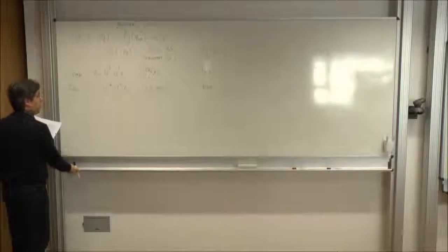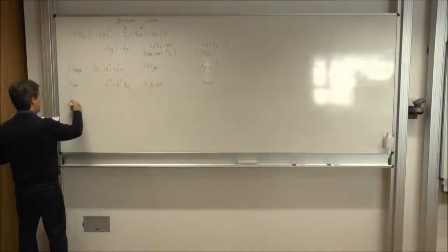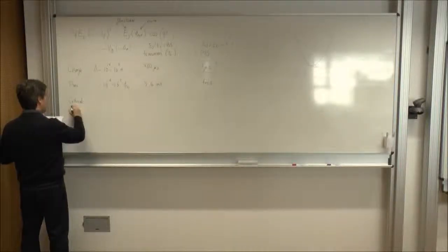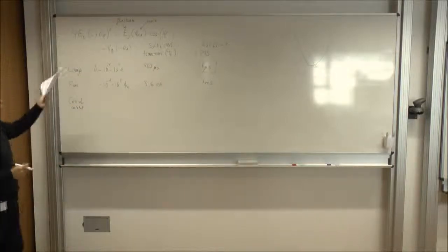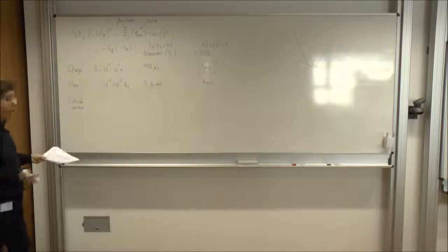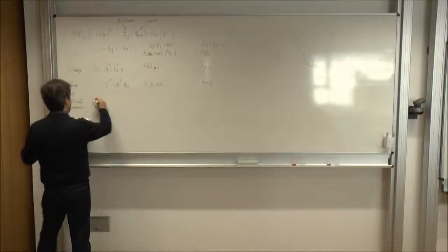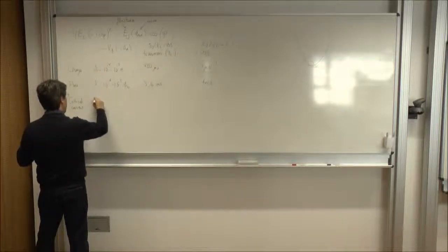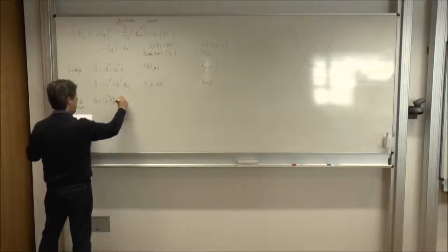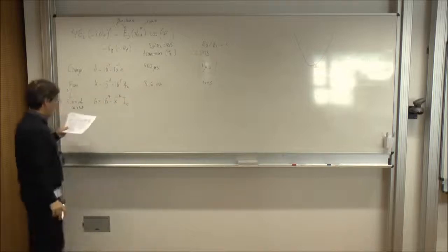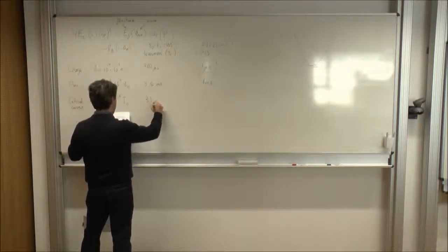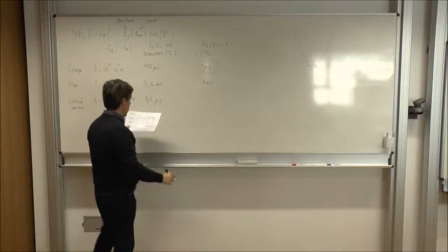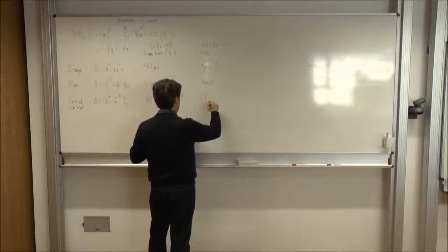But there is another source of noise, which would be critical current fluctuations. Your Josephson energy fluctuates somehow. These are now the parameters that appear in the slow noise, 10 to the minus 7 to 10 to the minus 6 of the quantum of current, and you have 35 microseconds here and 17 microseconds.